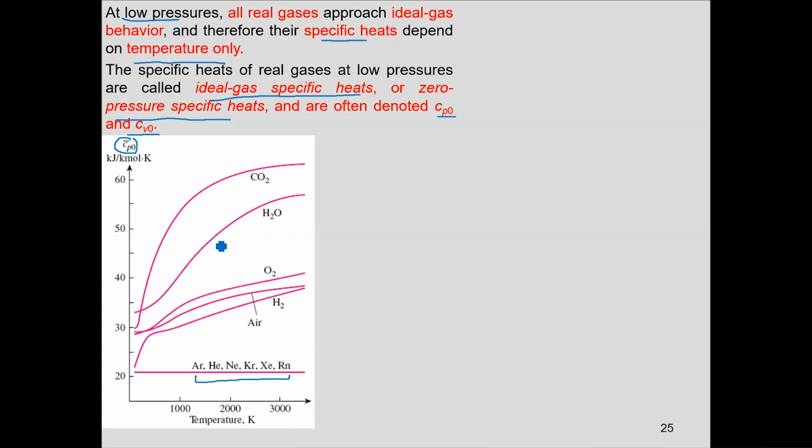The essential thing over here is, now you know that Cp and Cv are a function of temperature only for ideal gases or real gases that behave ideally. In order to calculate delta u and delta h, you need to have a relationship of Cp and Cv with temperature.